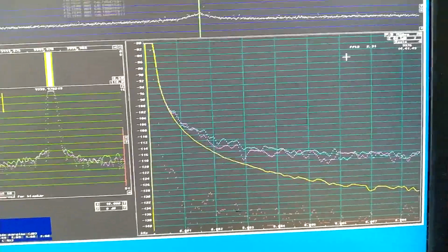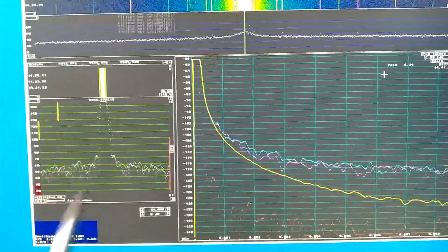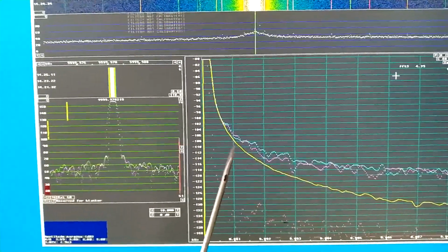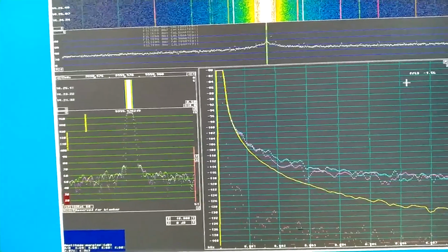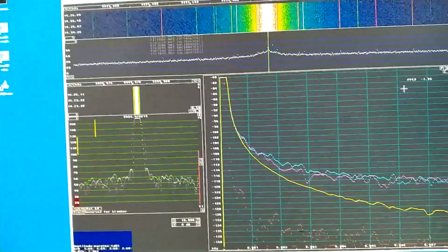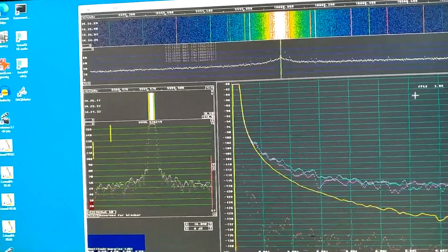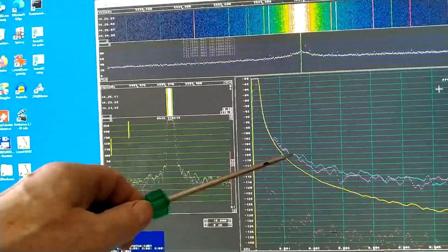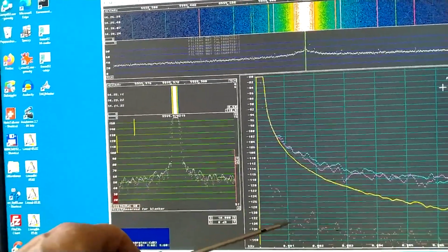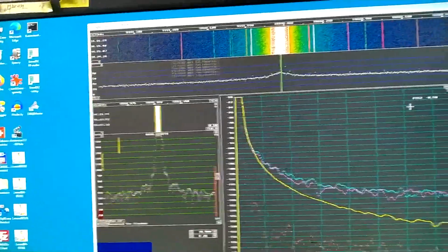Now I'm using the SDR-IP units, and of course the phase noise at 1 Hz is still minus 108 dBc per Hertz. And the signal-to-noise ratio for the measurement, as the distance between the phase noise, real part, and imaginary part, is very large, 30 decibels.